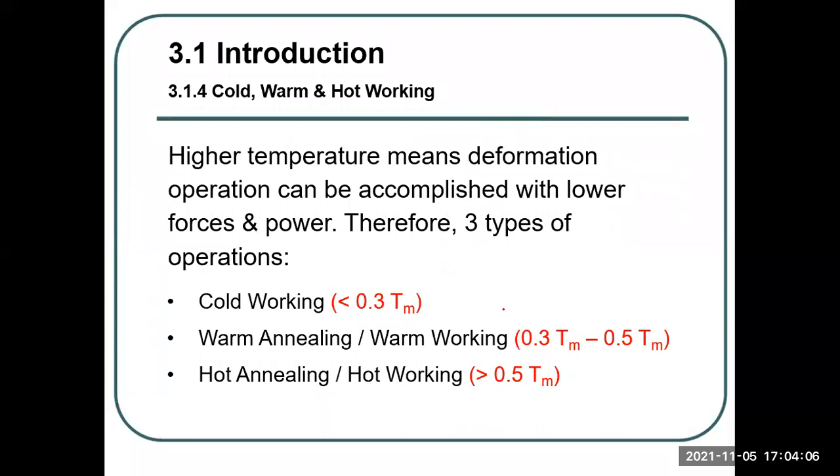Okay, then based on different temperatures, we can divide it into cold work or hot work. Higher temperature means the forming operation can be accomplished with lower forces and power. Therefore, there are three types of operations: cold work, warm work and hot work.